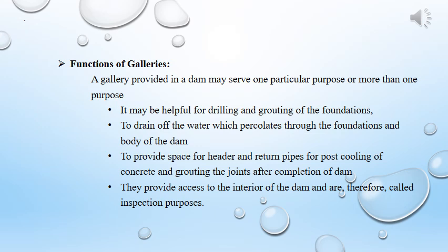The function of galleries. The galleries are provided for the following purposes: to provide facilities for drilling and grouting operations for the foundation, to drain off the seepage water through the body of the dam, to provide space for header and return pipes for post cooling of concrete and for grouting the longitudinal joints after completing the dam, and to provide access to the dam interior for inspection.